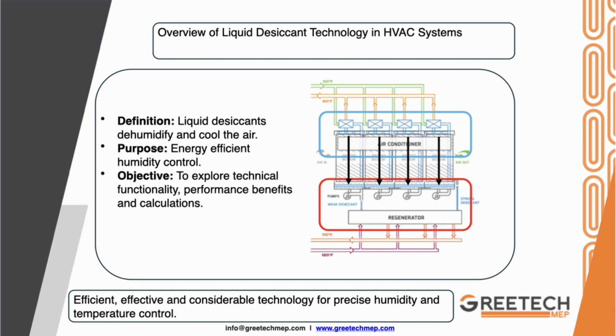The liquid then arrives at a container already as a mixture, which is the one in the upper part of the red box. This mixture includes 2 components. One part is the water condensate, and another part is the desiccant liquid. This mixture is pumped to a regenerator, which heats the mixture in order to separate the condensate from the desiccant liquid. This, already separated, returns to the conditioner to be cooled again and continue with this continuous process. This is a process of cooling, dehumidification, and condensate separation.